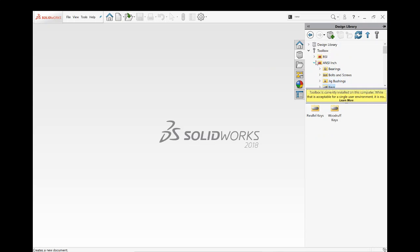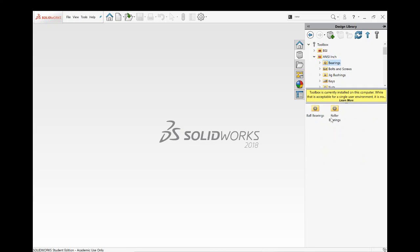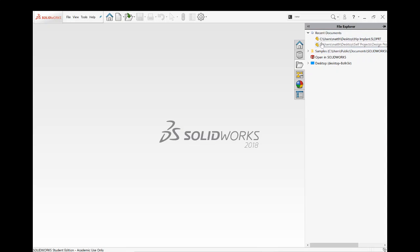For this, you have design library. So if you have a toolbox add-in, you can go here and do bolts, screws, bearings, and they have things pre-listed. So you can use these and drag them onto your part or assembly rather than having to make them yourself. So it's a really cool feature. Over here is your recent documents.